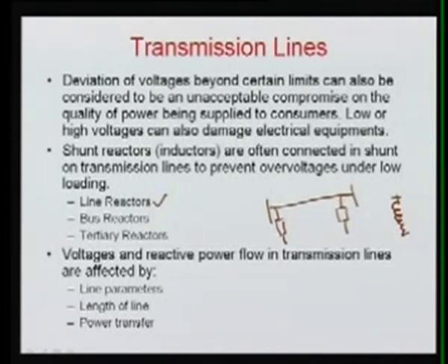No doubt we use circuit breakers here again for protection and maintenance purposes, but the reactors are always connected in the system, especially in 400 kV transmission lines. If the line is more than 200 kilometers, we have to connect line reactors at both ends of the line, unless, let's suppose, you have a generator here, that